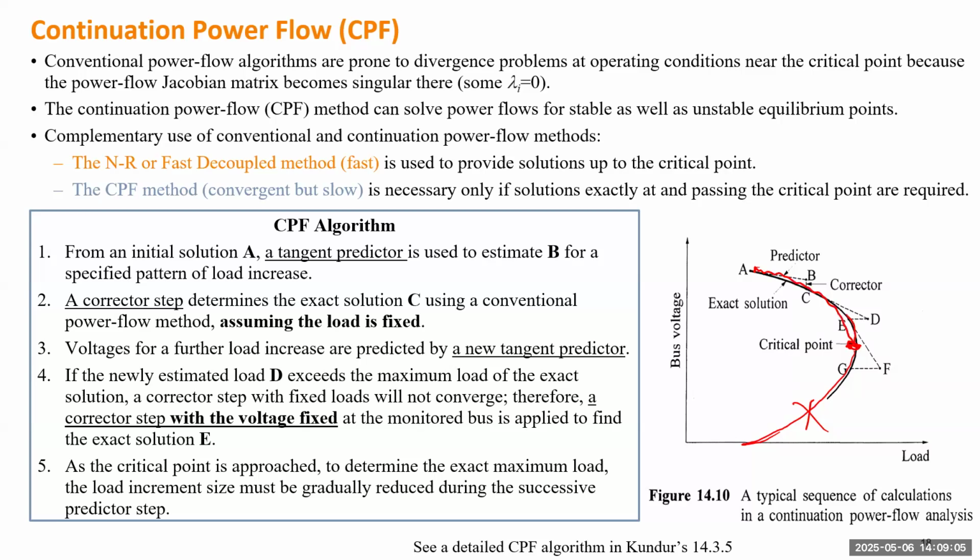Because you do have operating conditions there. But when you operate beyond this critical point, even if the software can give you that lower part, that may not be correct because you have to assume the load model to be this horizontal line, which has the voltage constant no matter what the power is. So that doesn't exist in the real world.